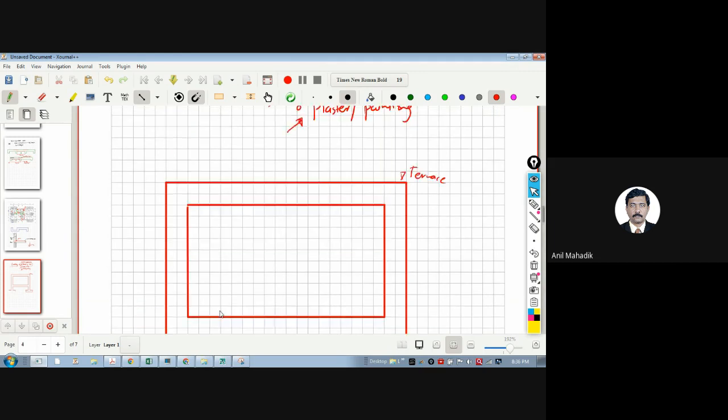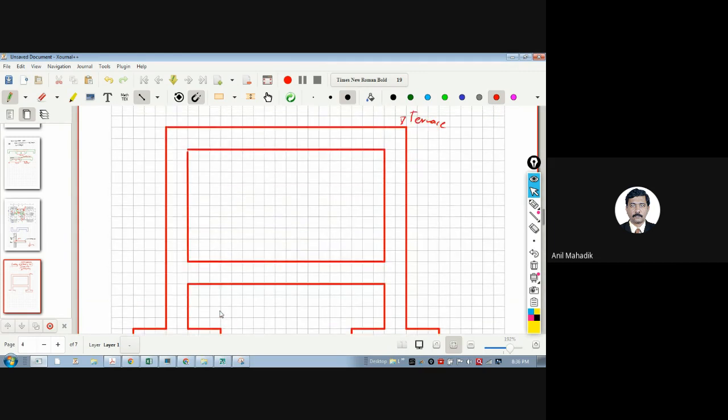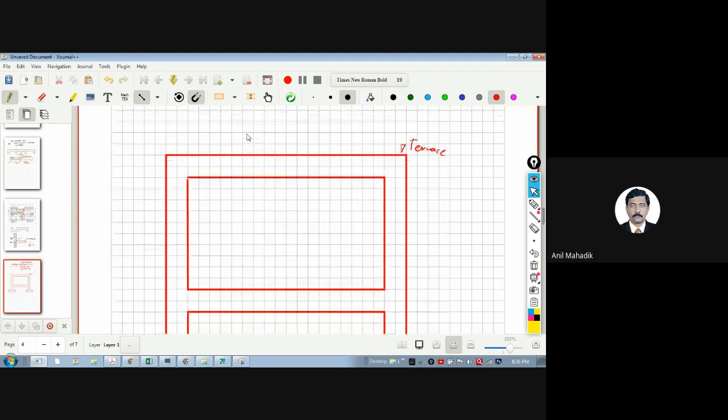Okay, so this is your building. Now you're asking what to do regarding the column. Say, if you are assuming this beam as a fixed end beam, generally whenever the beam is resting on the column, we assume it as a fixed beam. Yes or no? And in that case, we have a bending moment like this. This is your bending moment, and you provide main steel over here for the beams.